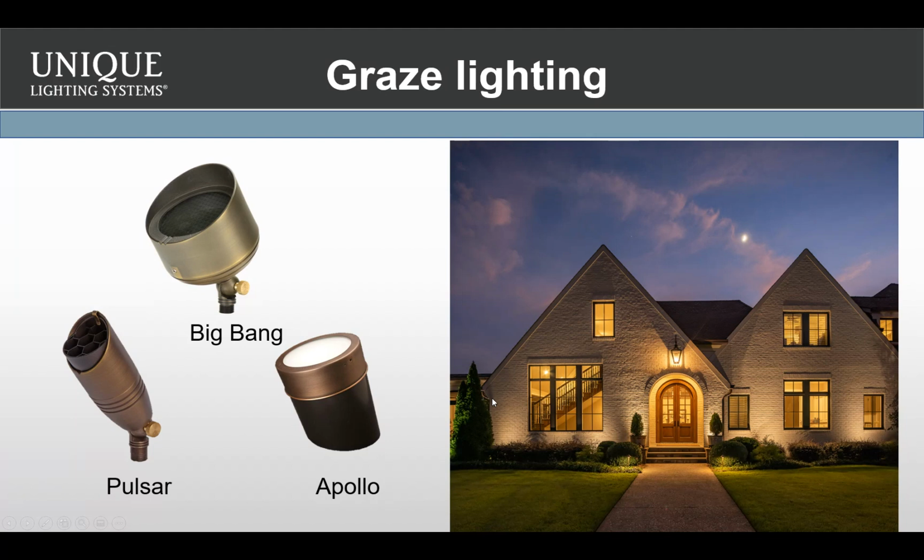The second thing this does is give me control of the windows. Now I can place these fixtures in between the windows rather than trying to spotlight it from the back. The other benefit is, I would venture to guess that 90% of the homes out there have some sort of sill. So that sill plate will help keep the glare from the light getting into the windows. If someone's in here and there's a knock at the door, when they look out the window, they're not looking at a big spotlight in their face. They can see who's out front and then open the door from there.